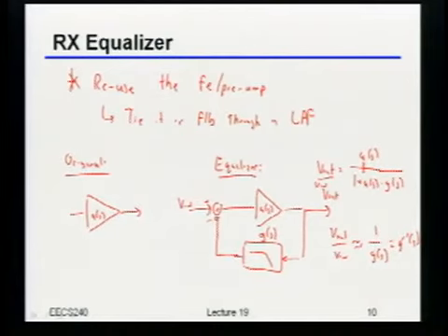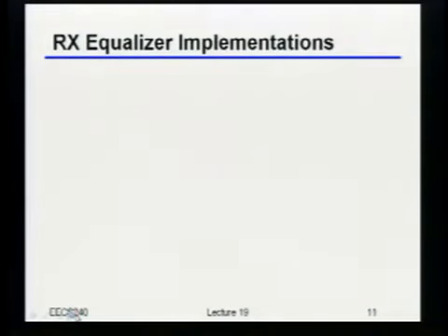Okay, so let's take a look at how we could really build something like this in an actual circuit. Let's start with the simplest thing that matches that block diagram the closest. Let's say I start out with some original preamp, something fairly simple, just a common source OTA.